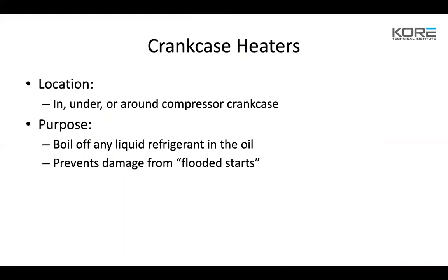So, crankcase heaters, it's a good topic for today. With it being cold outside, the heater is under or around the compressor crankcase. How many of you guys, when you do your checks in the cooler months, check the amp draw on your crankcase heaters? If I challenge you guys to do anything for the next few months, let's make sure that anytime we're working on these outdoor units we throw an amp clamp around those heaters.